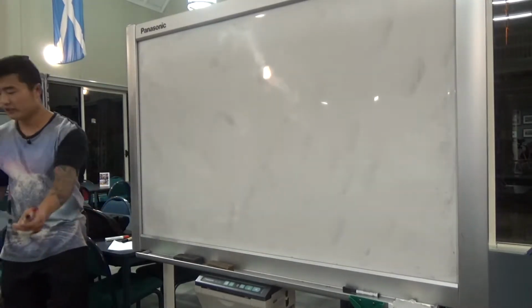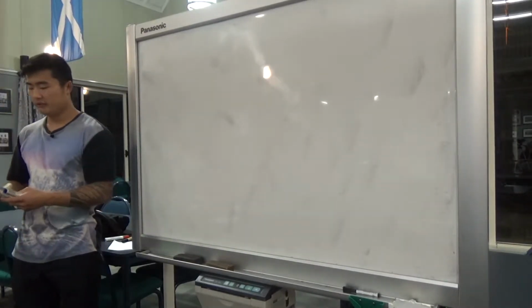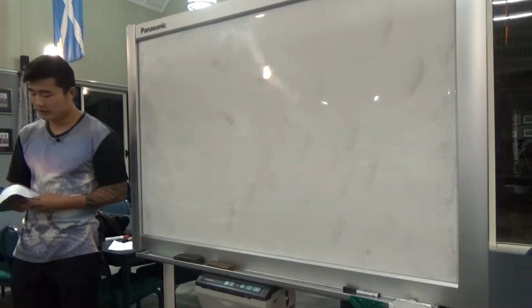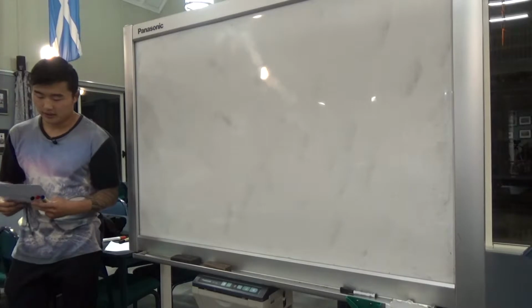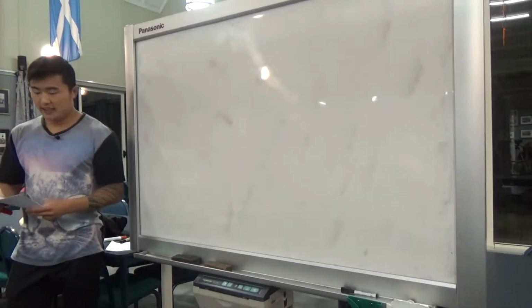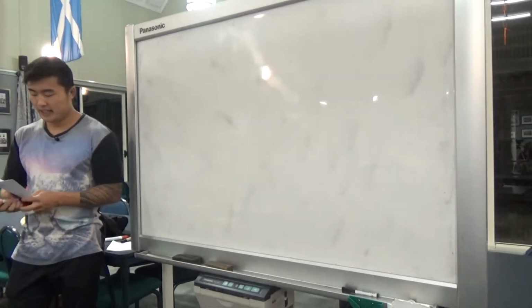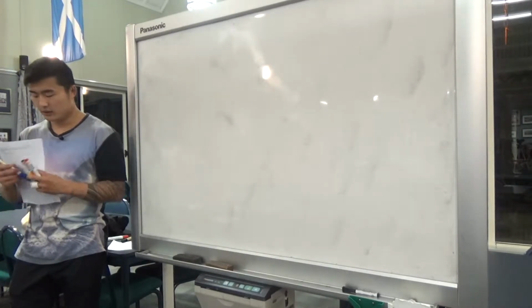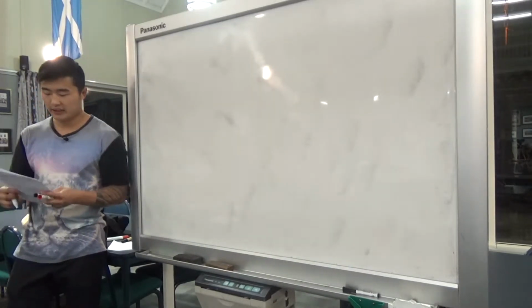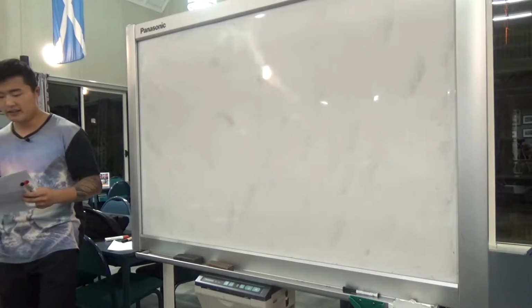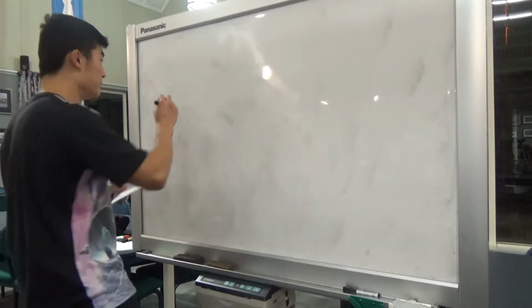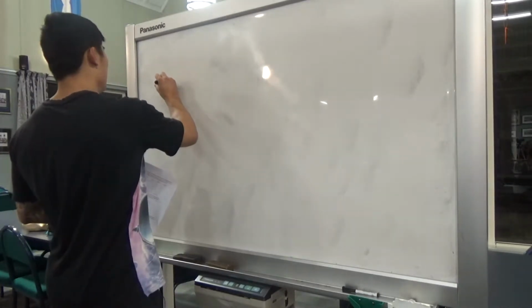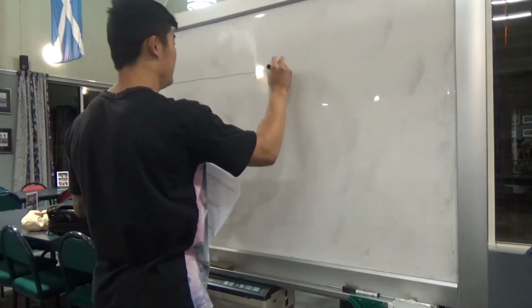So number 4, we have a 4 meter long, thin, rigid, uniform plank with a mass of 16 kilograms lying horizontally on the ground. Your 24 kg brother is standing on the plank 1 meter from one end. What force will you need to exert on the other end of the plank to lift it off the ground? So we're going to draw our plank. So here's our plank.